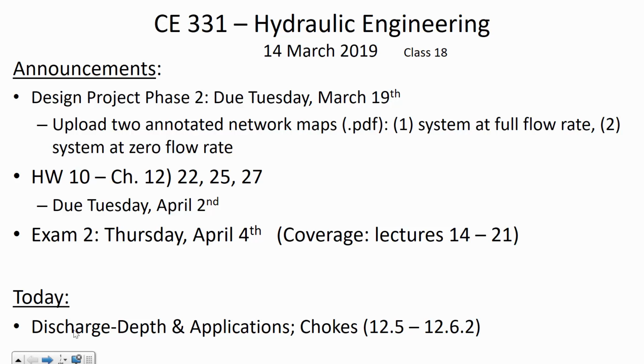And at the extreme, when you have interruptions in the channel like that, it can choke the flow. And by choking, what we mean is that there's some sort of an obstruction there that's causing the water to pool upstream. And we'll talk about why the water pools when we put an obstruction. Sometimes it pools, sometimes it doesn't. So we'll get into all of that today, and here's the corresponding section from the book.